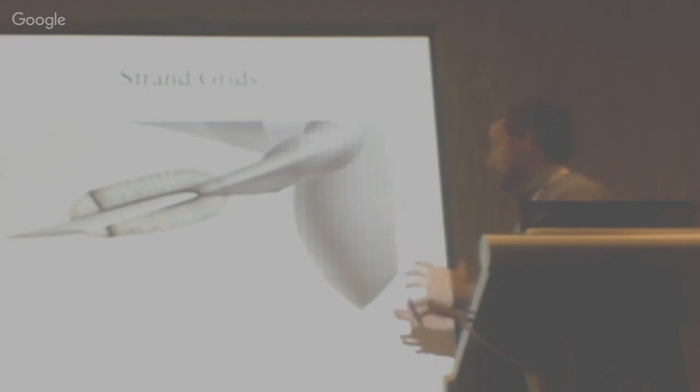And the goal is to have a really fine mesh density near the object so you can resolve really tiny features, especially good for turbulence. You can put it really in there in the laminar sublayer. And then to eventually work out to a coarser density to save on computational power.